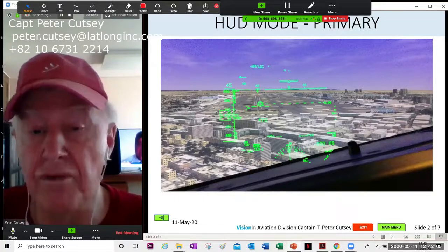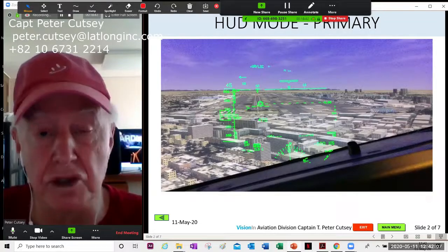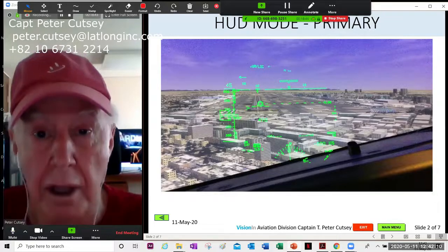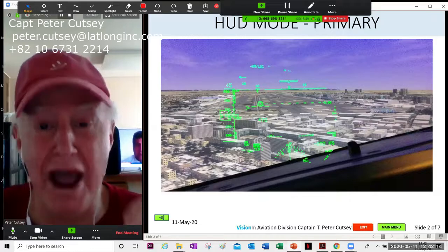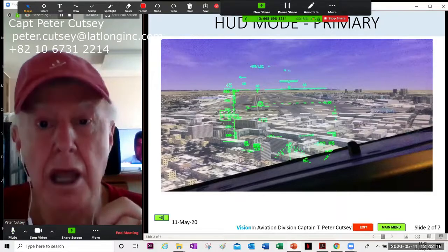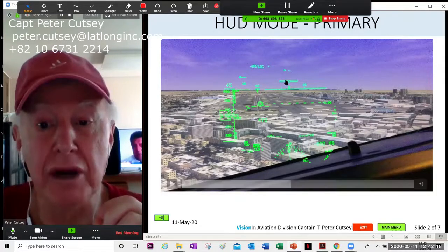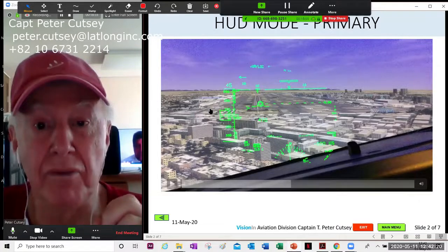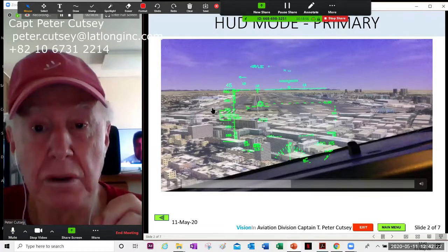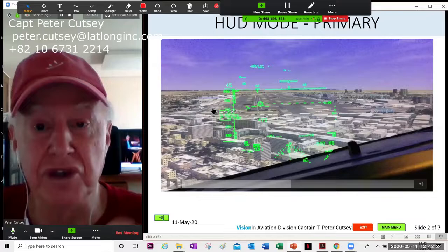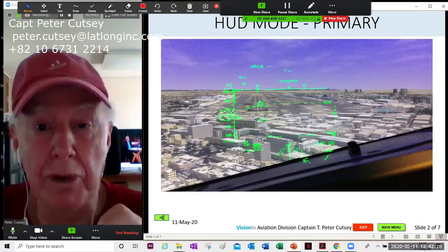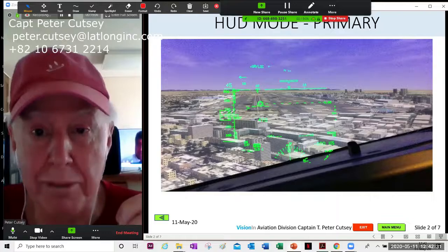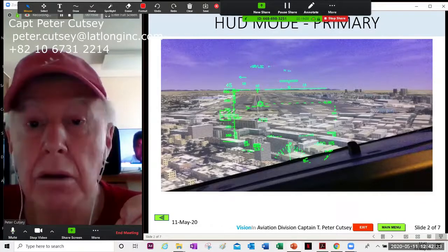If you're at 5 degrees of flap at 60 tons downwind doing a traffic pattern, you'll be pitched up at 6 degrees above the horizon. Your bore sight will be at 6 degrees above the horizon. The aircraft symbol will be 6 degrees above the horizon. Your altimeter will indicate you're bang on the altitude you want to be at. You're not climbing or descending.